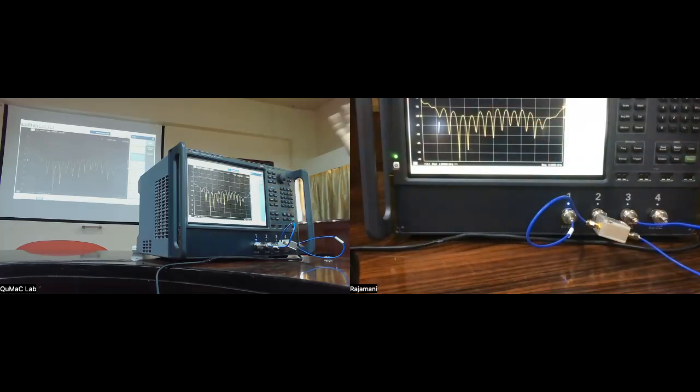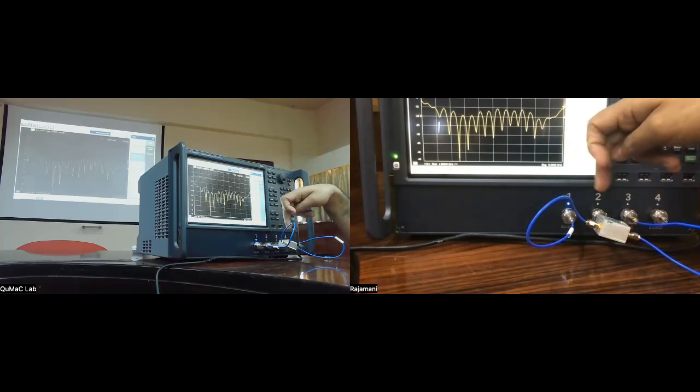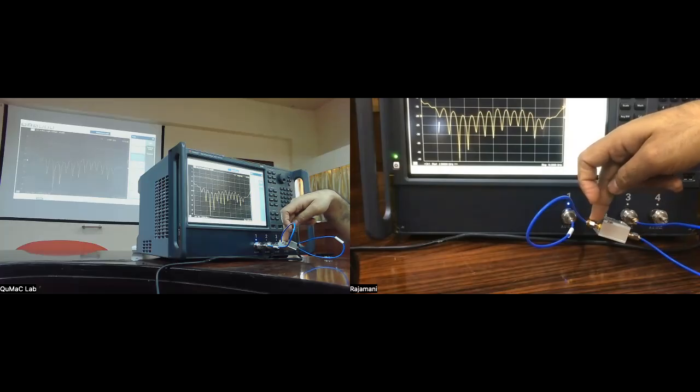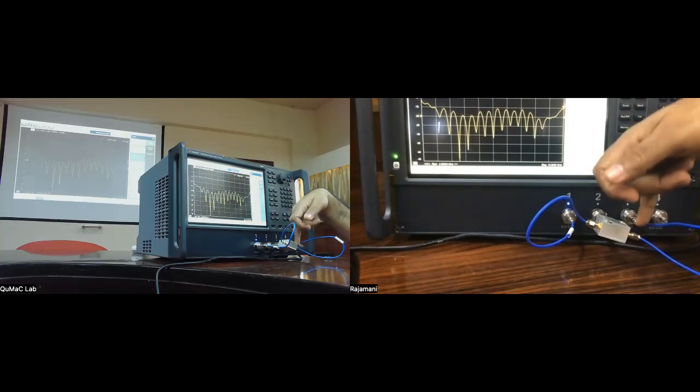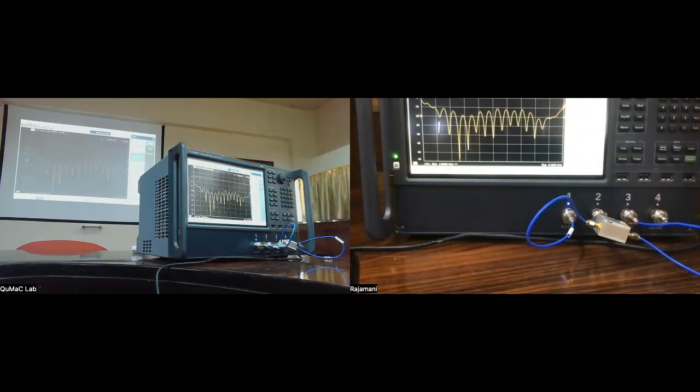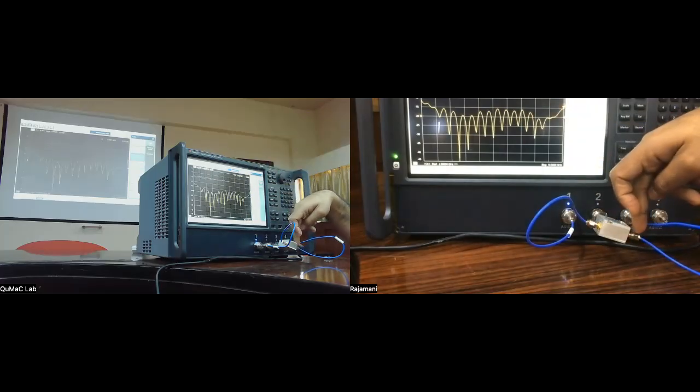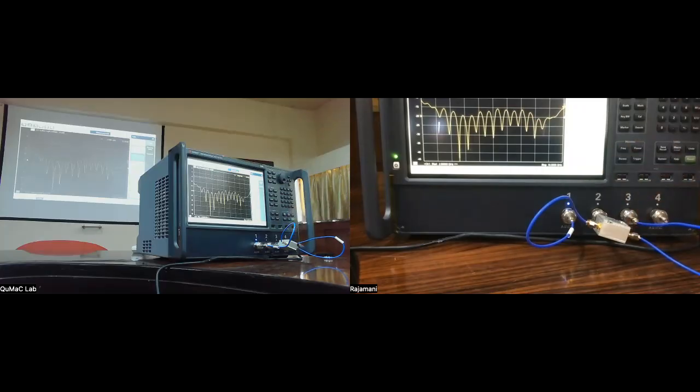This is again not unphysical, right? This is not violated because these two combinations of port, we are just looking at it for the first time. But what does this mean? I send in power from one of the output ports. 50% of that power comes to the common port. No power, in the ideal sense, is coming to the other output port. And we know that it's not reflecting. So what's the only interpretation of what's happening to this power?